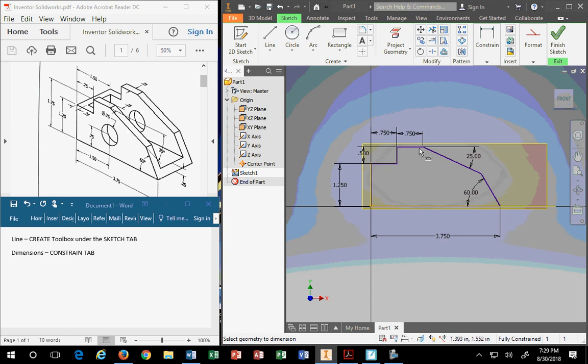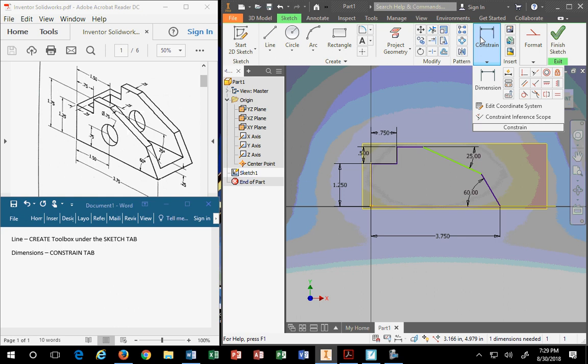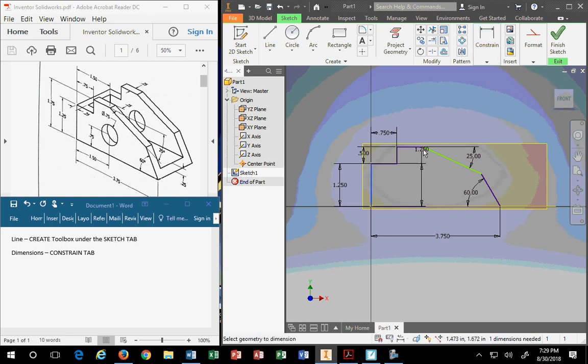You cannot leave these dimensions on this drawing the way they are. And you can never give them to production because they will make it wrong. The tolerance is too great. Because stacked tolerances are dangerous. You actually have to delete this one and put in the correct dimension, which is from side wall to end point 1.5. Because now the tolerance isn't compounded. Because when you have two dimensions butt up next to each other, that means you're compounding your tolerance across all those objects. You can't do that.